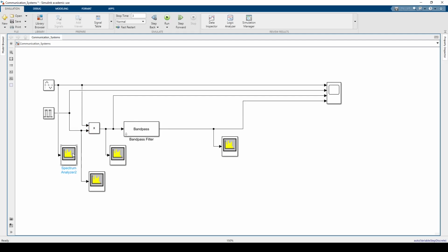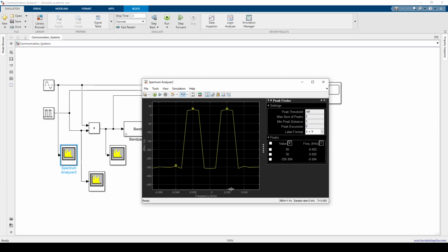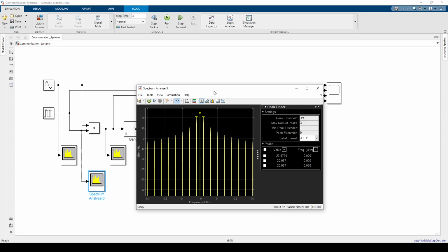If we look at the spectrum of the sine wave, we'll have spikes at 2 Hz and -2 Hz. This is the spectrum of the square wave. The center spike is harmonic 0, or the DC offset. And this is the fundamental frequency spike. And then since the square wave has a duty cycle of 1/2, every second harmonic is going to be missing.